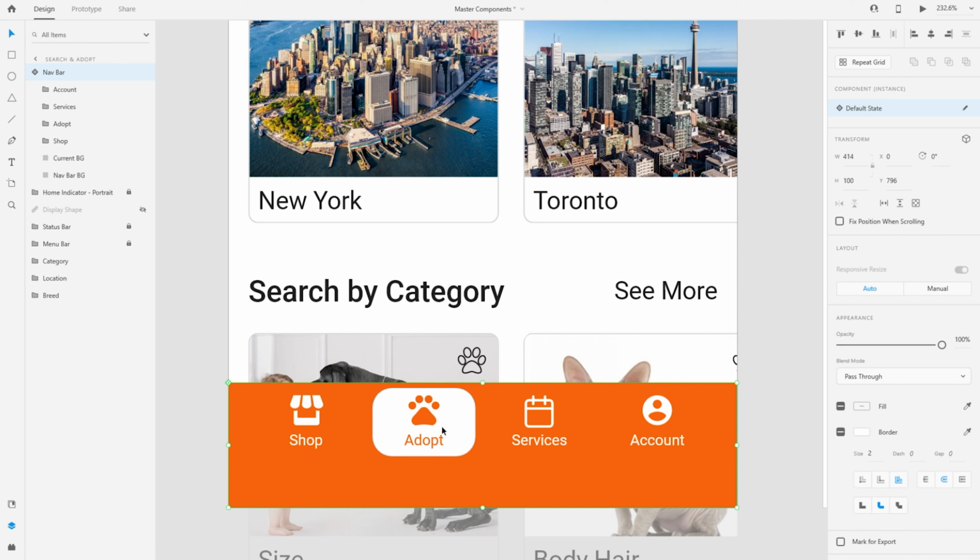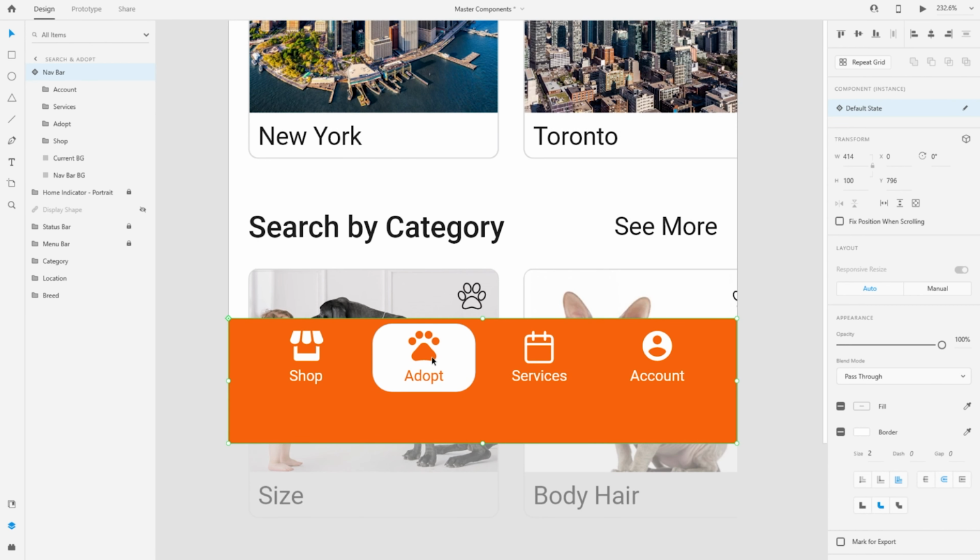So if you want to make any edit in an instance of a component, you can pretty much make edits to any style related property on the properties panel, and that will not affect the master copy or any other instance. If you've made any overrides in one particular instance, you can see that as well. If you look again at the top left corner, it has changed into a diamond with a green dot in the middle. That signifies that some property in this instance has been overridden.